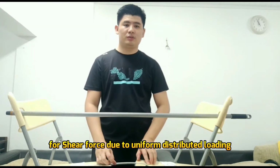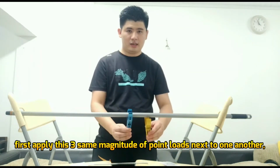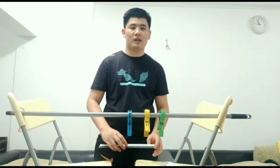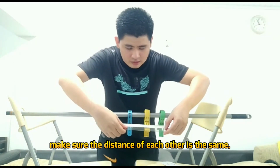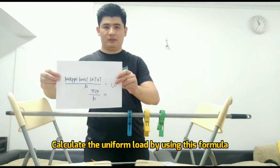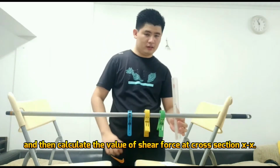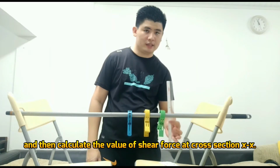For shear force due to uniform distributed loading, first, apply at least 3 same magnitude point loads next to one another. Make sure the distance between each is the same. Calculate the uniform load by using this formula. And then calculate the value of shear force at cross-section XX.